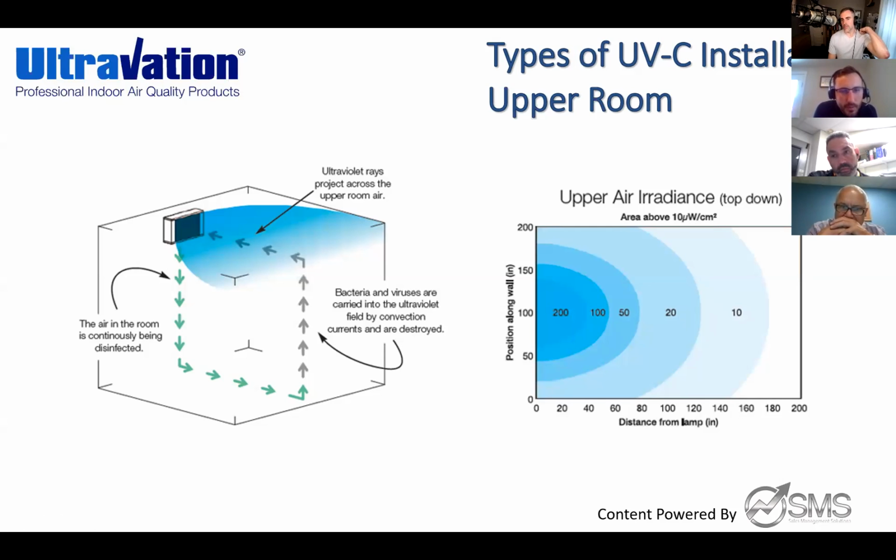Yeah, people don't realize this, there's a natural convective flow of air, right? Cold air on the bottom of the room, hot air on the top of the room. So there's always a natural movement of air happening without fans. And that's what this is helping deal with, right? There's going to be a natural flow of air, hot air is rising. So if they need to increase the level of air radiation in a space, this is how you could target it. And this is actually called out in chapter 62 of the ASHRAE handbook on UV guidelines for upper room applications. This was in their handbook.